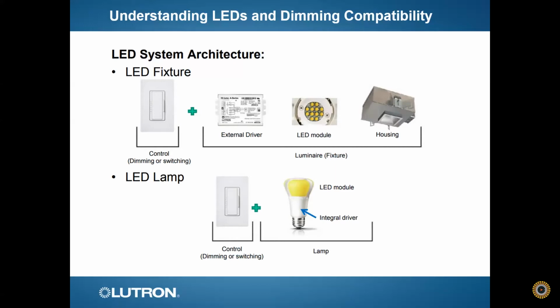They've got the LED module, they've got a driver, and where the challenge with a lot of the LED bulbs comes in is you're taking a driver that typically is, in a package, around 4 to 5 inches long, 4 to 5 inches wide, and maybe an inch or two tall, and you're squeezing that down into the Edison base, this little screw-in base of a light bulb, and expecting that you're going to get the same performance out of that guy as you're going to get out of the brick that goes into a dedicated fixture.